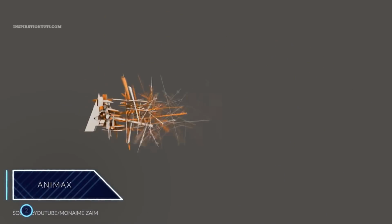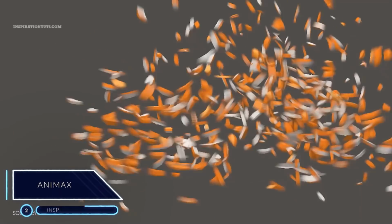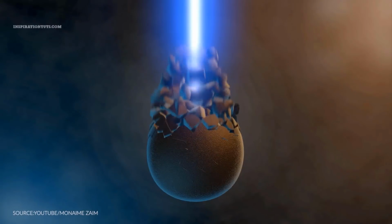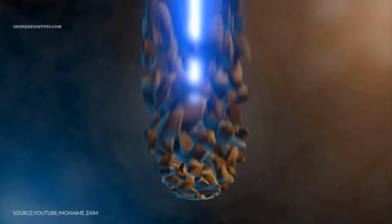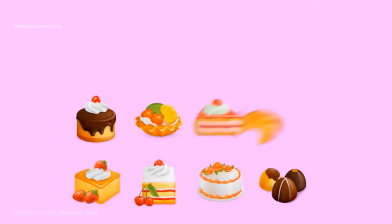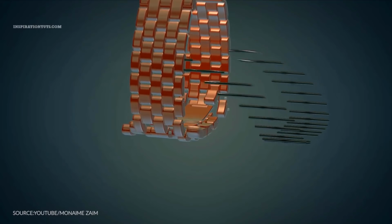Number 2, Animax. Animax is a procedural animation system for Blender, useful for animating multiple objects. It allows you to create complex animations that are hard to achieve using Blender's built-in animation tools. There are tools for splitting and shattering a mesh object into pieces and converting the procedural animation to keys. The animation is procedural, but it is possible to keyframe a lot of parameters for more complex animations.